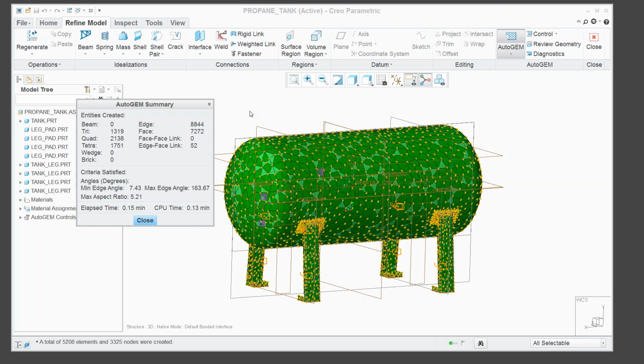Creo Simulate uses P elements, which supposedly allow you not to worry too much about mesh. And in fact, they will give you pretty good results, even if your mesh is kind of mediocre. But if you have good mesh, you will get even better results. And my point here is that it's really easy to get good enough mesh without spending a lot of time on it. So now we're good to go.